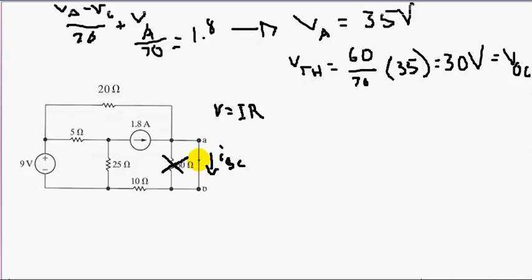The voltage across a wire is 0. And when you divide your voltage by your resistance, you have 0 current. So this acts as an open circuit right here, and here, and here. So now what we have is just this current source and this wire connected to A, to B, and it'll go back to ground.